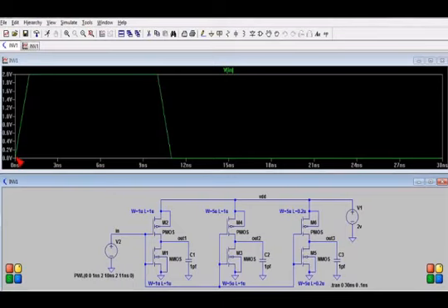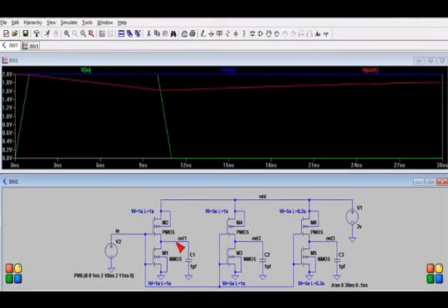And you see the input pulse switching up to a logic 1, staying at a logic 1 for about 10 nanoseconds, and then switching back to a logic 0 level. So let's probe our supply voltage and make sure it's at 2 volts. And that's shown here in blue, and that looks good. Now let's probe our slow inverter case and look at the output. So here we see that in red.